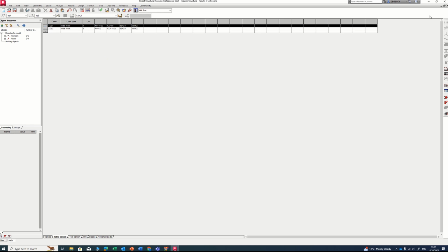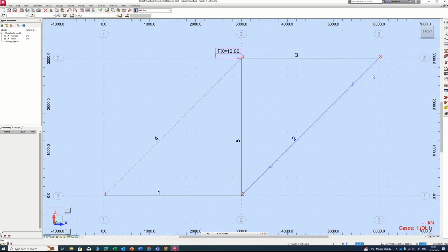So once done, then we can close this window by clicking on this one, and bring back these structures in here. So after that, what we can do is have a look at the support. So press this one, support is coming back, and then load symbol is already on, and then load case 1, load case 2, and load case 3. So that's the final one we're interested in. So for this bit, right? So now if everything's set, then you should be ready to run the analysis.